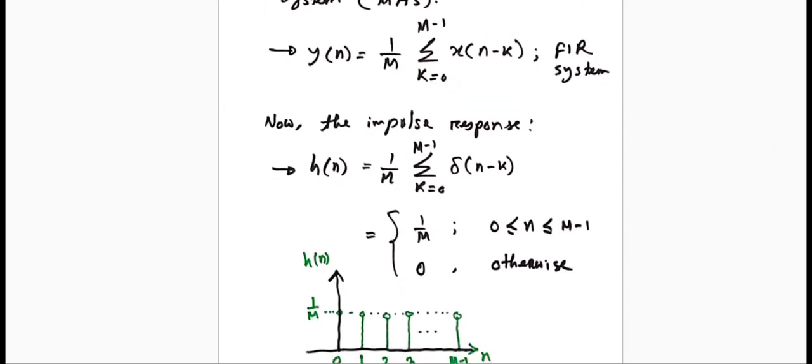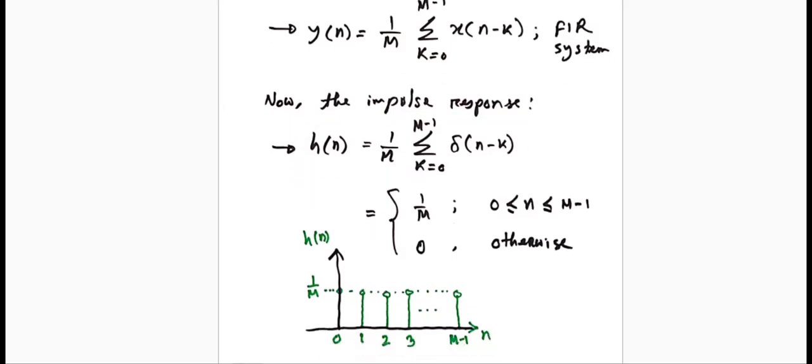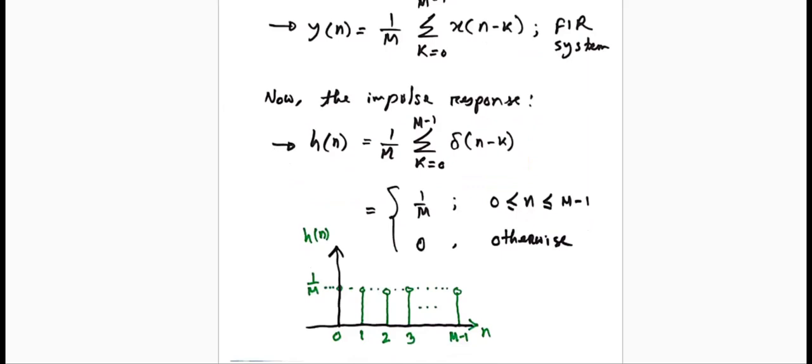Now the impulse response, since this is the system definition, how you can find the impulse response? The input should be given as a delta function, impulse. Input can be replaced with the delta function, and that gives you the impulse response of the system. So according to that notion, we can say that, okay, this is our impulse response. At any point of time in my lecture, if you have any confusion, please raise your hand for clarifications. So we got the impulse response.